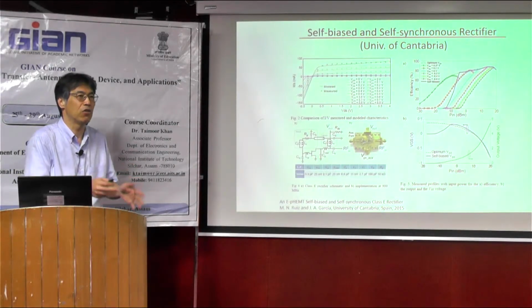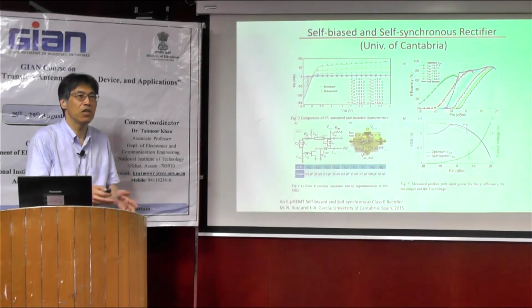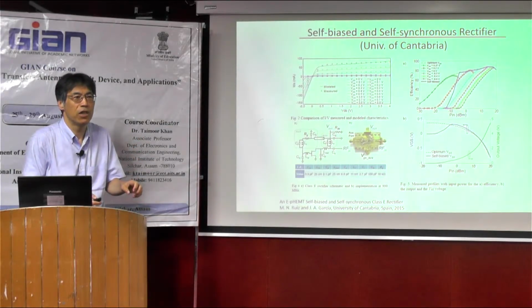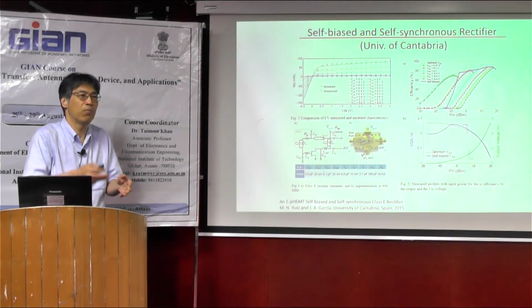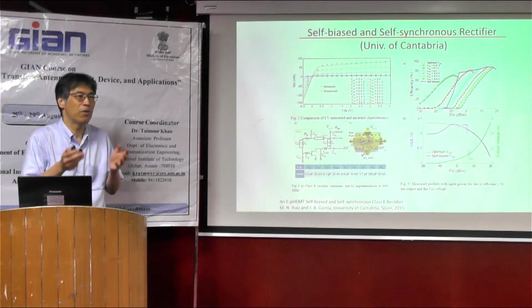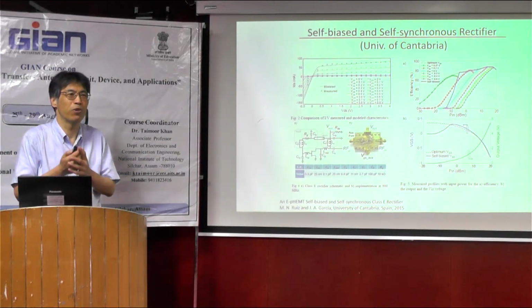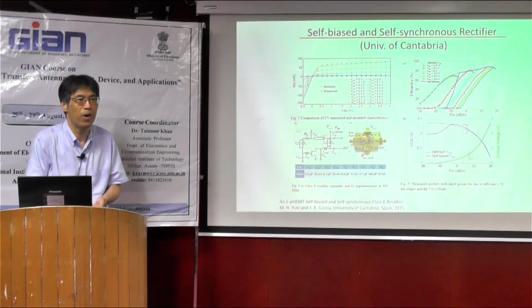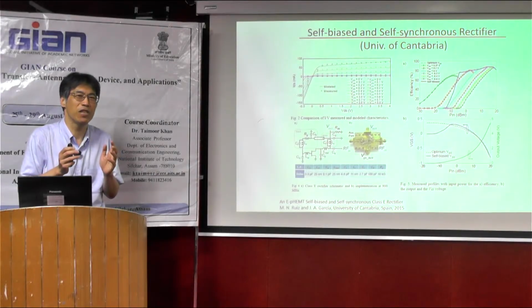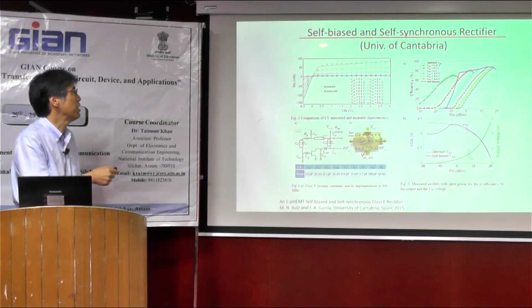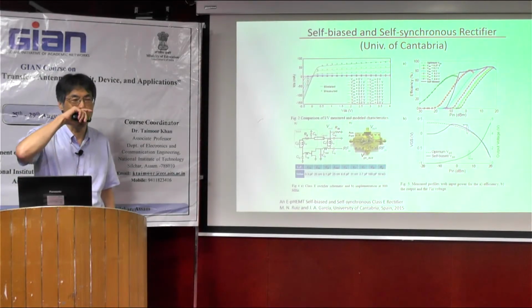Usually, a detector is a circuit very similar to the rectifier, but it is usually used in wireless communication circuits. For the wireless communication system, input power is very weak, so they add an extra voltage at the diode to overcome the junction voltage. But as I mentioned sometime in my course, if the user has a battery, of course we can do it. We can add the bias voltage at the diode, and we can overcome the junction voltage. But for a battery-free IoT sensor, etc., there is no battery outside. So this self-bias technology is very interesting, like our DC-DC converter.